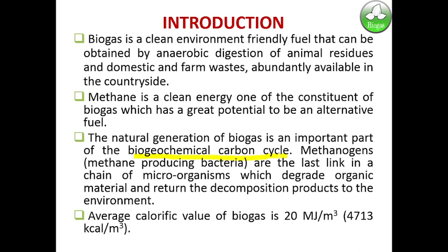Before bottling, the methane content is enriched from 55 to 95 percent, similar to CNG. As we have discussed, biogas contains other gases like carbon dioxide and H2S. So refining has to be done, and the methane content should be increased to 95 to 100 percent. This is the main thing: utilization, and how it can be stored for different purposes.